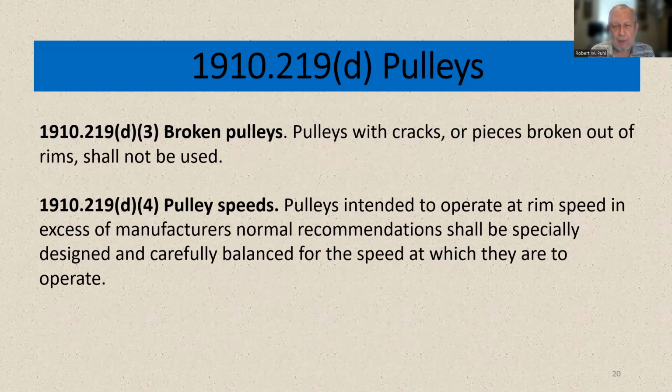Now that's something that you won't see anywhere else in OSHA that I can think of. If they're operated outside of the manufacturer's recommendations, that's probably going to be considered an OSHA violation. OSHA will look at manufacturer's recommendations. I don't know if you wrote up in Malta one time because the ammonia detector wasn't being tested in accordance with the manufacturer's recommendations. So when you buy a piece of equipment, any kind of equipment, read the stuff that comes with it, and that will give you a lot of information. If it says in there to lubricate this thing every 24 hours, then you need to do it.